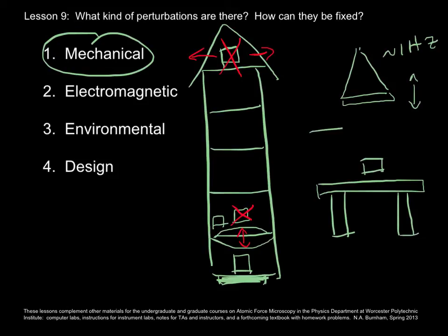What you want to watch out for is if in your ceiling you have a vent with air coming down, and you don't want to have air blowing all over your AFM. And not only air, but just acoustic vibrations in general. You need to shield it from the air flow from a door, from a hallway, from people talking. That shielding should also not only be mechanical acoustic, but also be electromagnetic, i.e. you should have some foil in there and ground that foil.